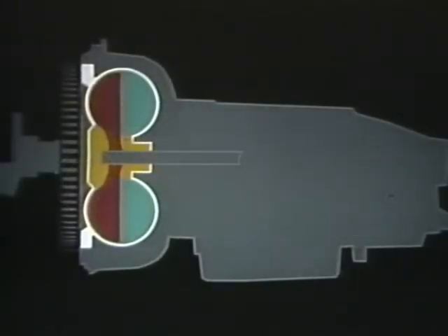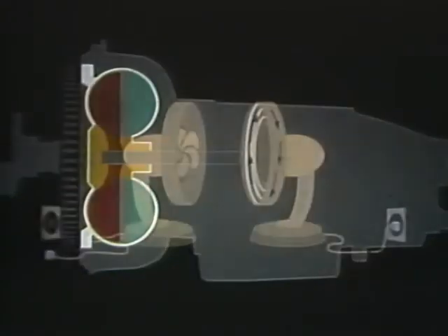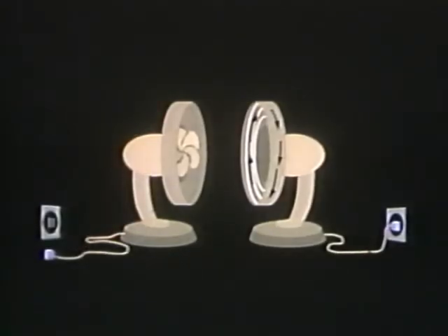Looking at the first requirement of connecting or disconnecting the engine from the driveline, we find that vehicles with automatic transmission use a type of hydraulic unit, which in its most simple form is referred to as a fluid coupling. The principle applied in the operation of a fluid coupling can be illustrated using two electric fans.